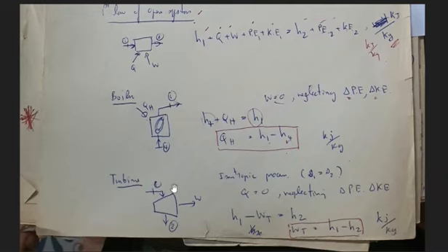So for the turbine, there is no heat exchanging, and we can neglect the potential energy and kinetic energy because the height of the turbine would not change, and the velocity of the fluid coming in and out of the turbine would be the same.